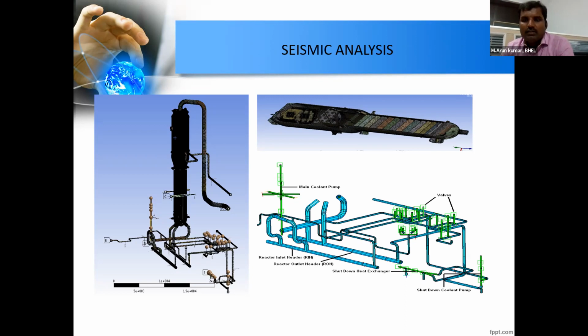We have done a huge modeling, and we have made so many couplings, and we have made the pipings. We have considered all the masses of valves, various pumps, various heat exchangers, various headers, which are connected to this equipment. So this exhaustive seismic analysis takes a considerable amount of time in design.